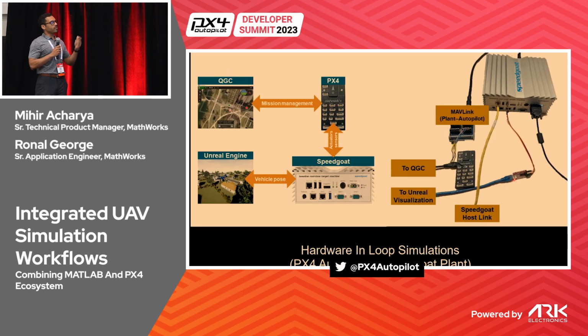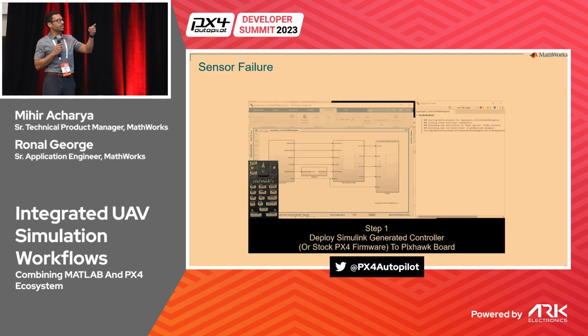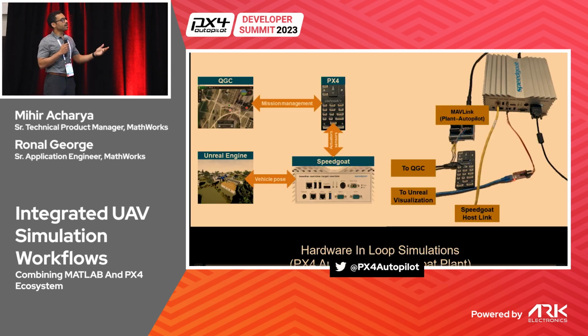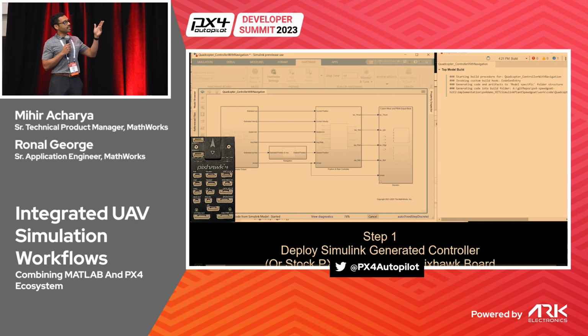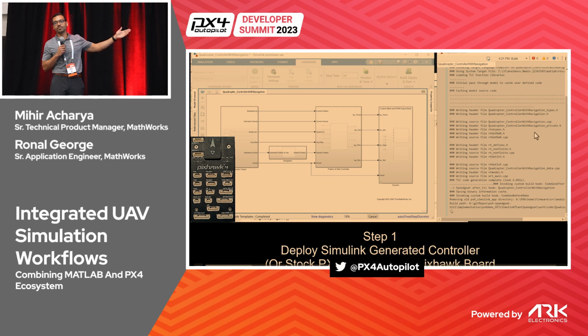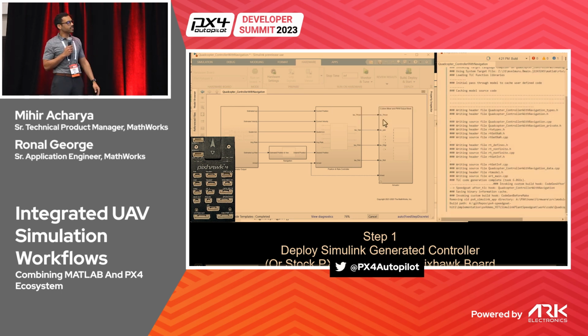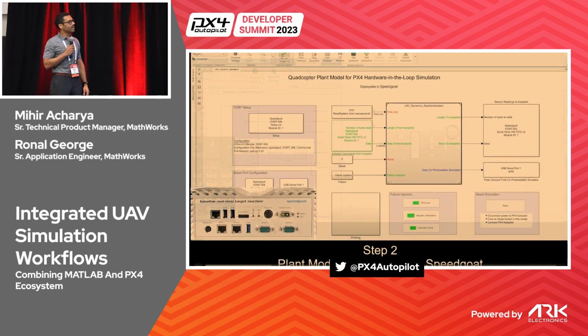What does that enable now? So if you look at this diagram, I have serial communications to the flight controller. I have telem data going to my real-time hardware. The first thing I want to do is deploy my actual controller. So that's my controller module. It has a navigation block in there in which it's going to avoid obstacles. That gets deployed, so it's fairly straightforward. I hit the build button. I have to make sure that I have serial communications with my PX4 board here. We use the PX4 FMU 4. We're going to update this for the 6X, which we just acquired.